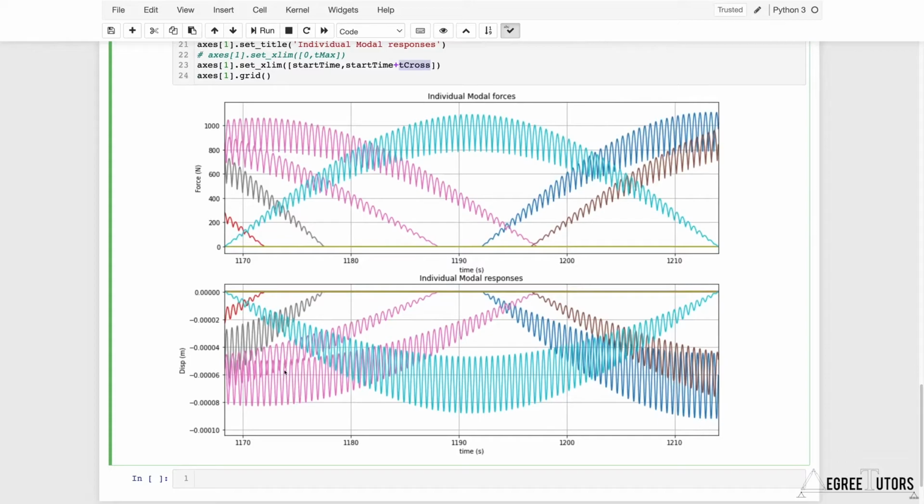And so if we were to generate the combined influence of all of the pedestrians within this window in time, for every time step we'd have to add up the values that occur at that time step. So for 1170 here, we'd have a contribution from the blue guy, from the red guy here, from the grey guy, and then 2 of these purple people here. And so that's what we're going to do next. We're not going to actually cycle through; it's going to be one line of code just to add up all of the rows within our crowd force and crowd response data structures.